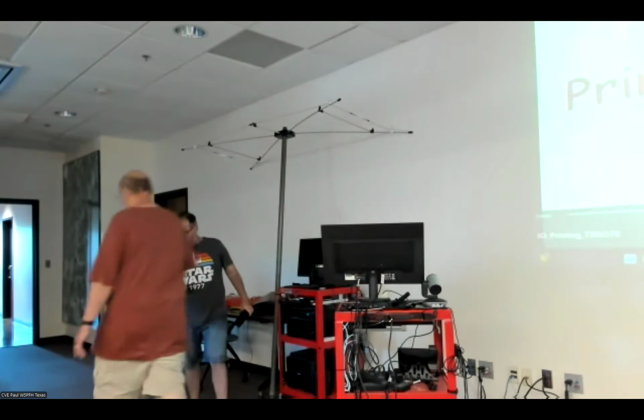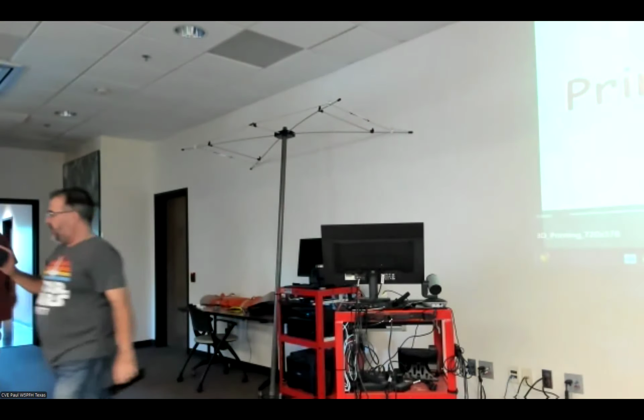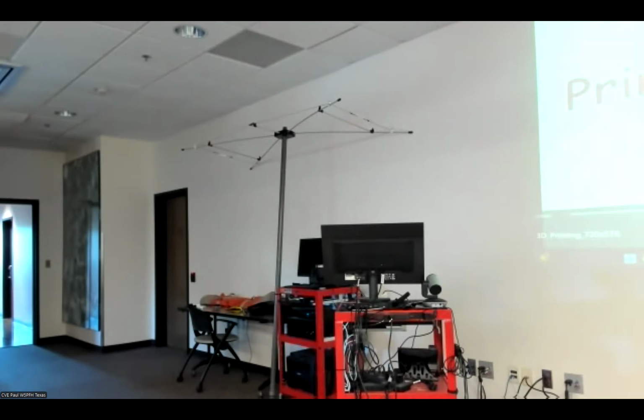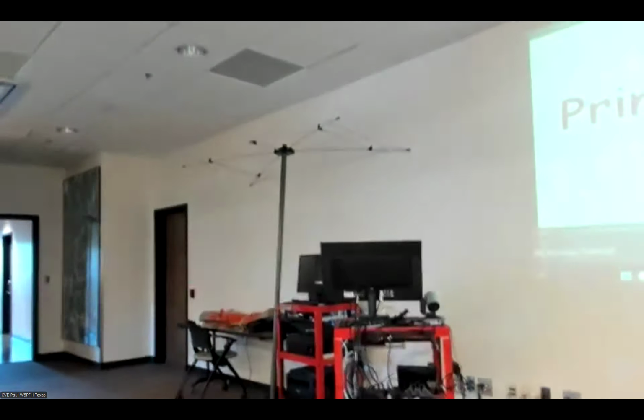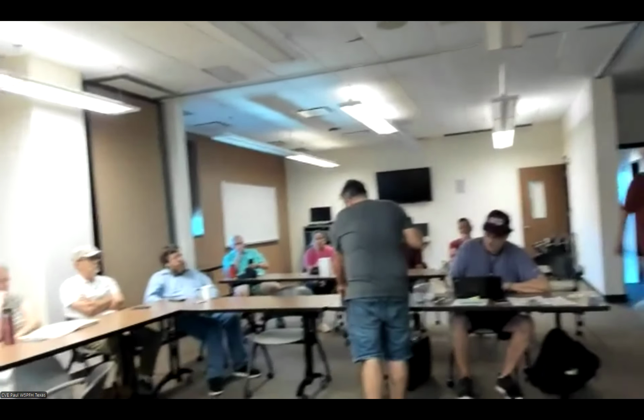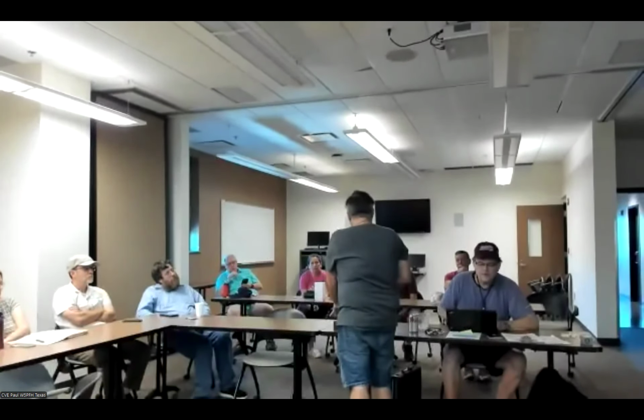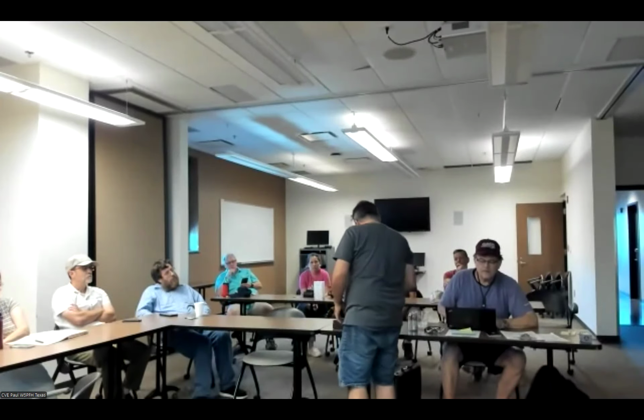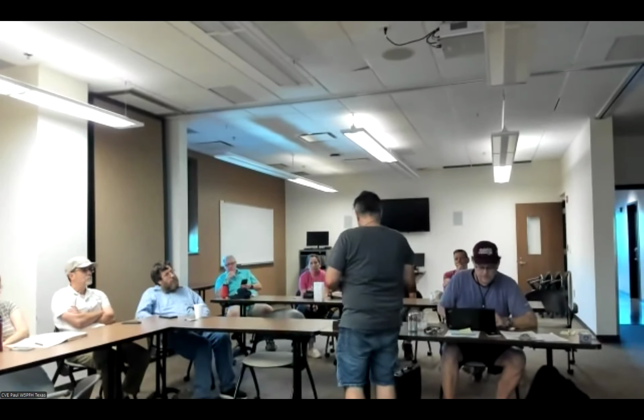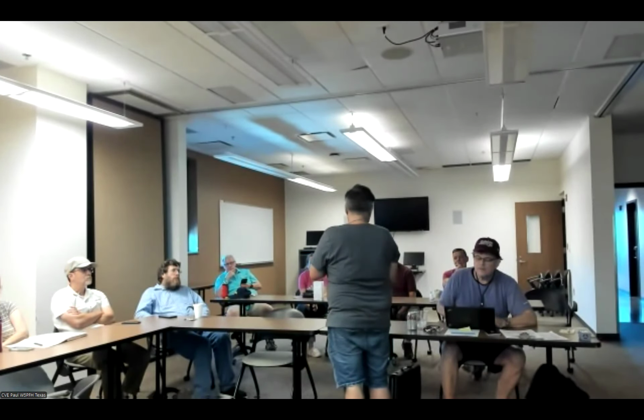So what I ended up doing was recreating the blood pressure machine itself, CADding it up and extruding that, and then building a housing for it. And the best way I found to do it with the geometry was to print this, and then design a solid box to subtract that from that to get the initial spacing for it. So this is 10% infill, just because I was doing it to get the outside geometry. This took about 20 minutes.